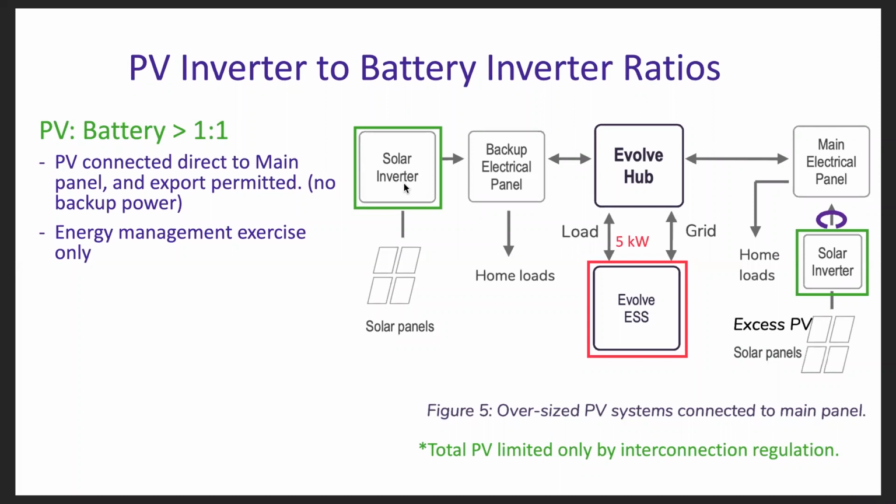As far as any of the other solar inverter manufacturers, I don't know of any other way, without using a relay, of course, that any of those other manufacturers will allow us to curtail them or to derate their inverters when we go to a backup mode.